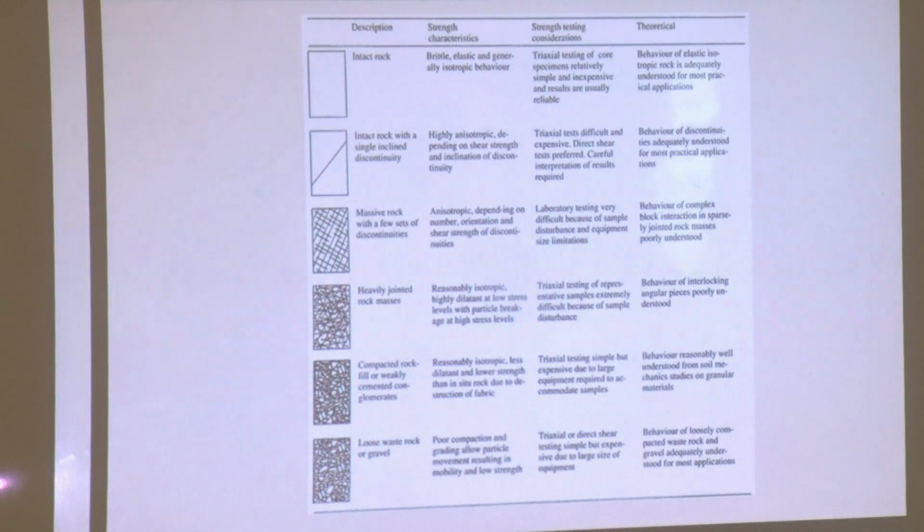What is the possible reason? When the tunnel was being driven at 33 meters, I doubt it was feet, it interacted with a sandstone layer. That sandstone layer is very porous, and there is a local water table that could not be predicted earlier.